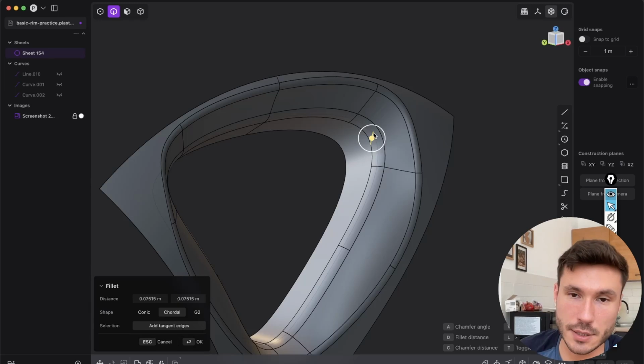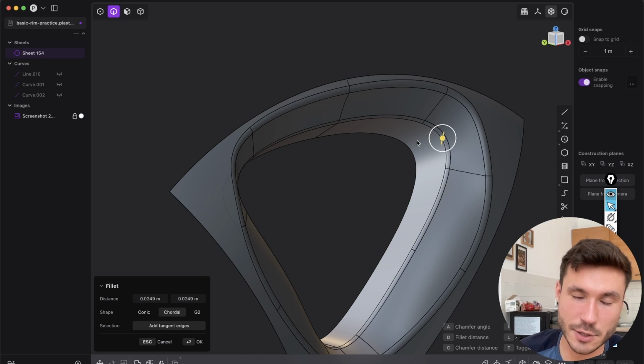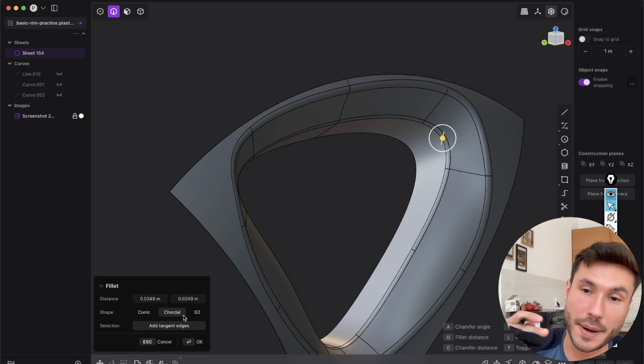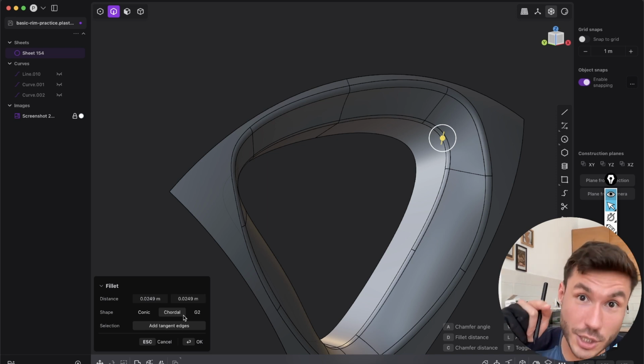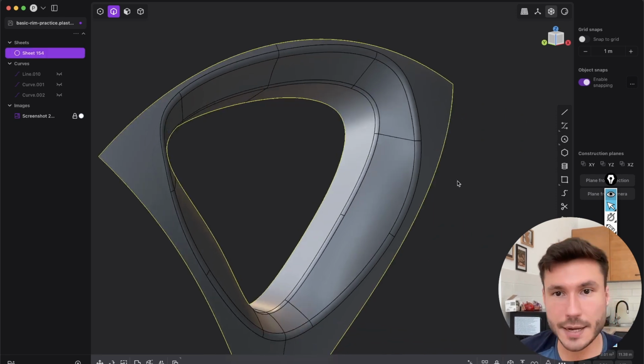And it works in this case, that's fine, because when I was practicing before the tutorial, it did not work with this technique. So if chordal fails for you, no problem. After this video, so we are still not done, watch the link in the description. I have a tutorial on how to create manual fillets with the pipe, so it's everywhere the same distance. If chordal doesn't work, watch it after this video. But in this example, right now it works, so press OK.